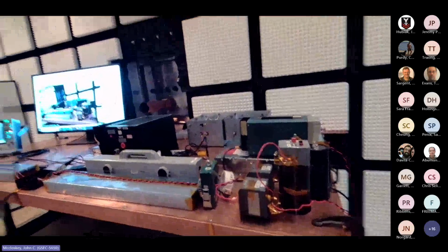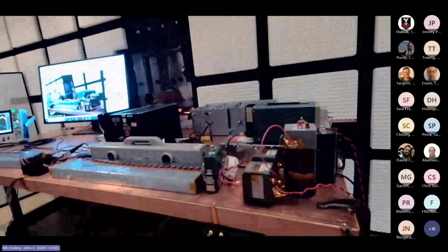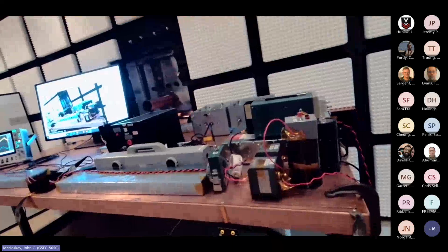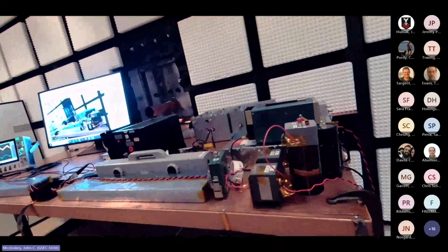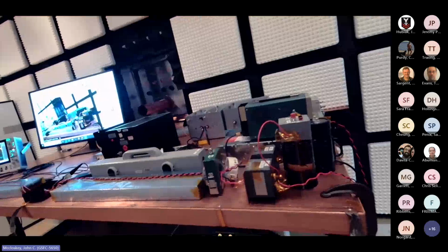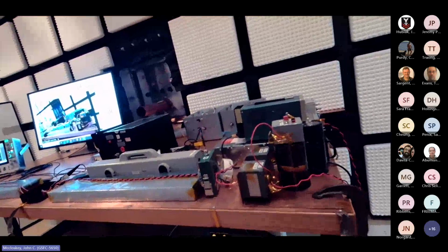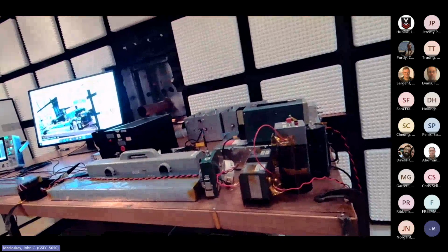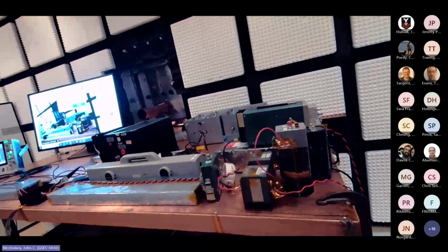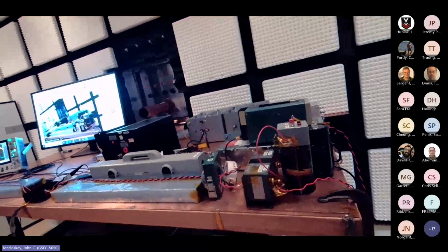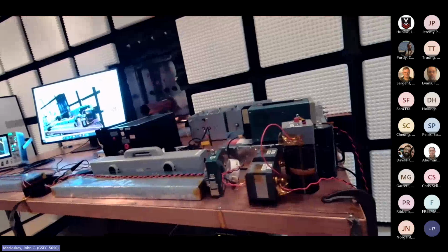So as I mentioned last week, on a military platform the power distribution is similar to what it would be in a large building, where you're running 60 hertz facility power over a long pair of wires for a particular circuit in one area of the building. That common source impedance that all those loads are connected to can be quite high.